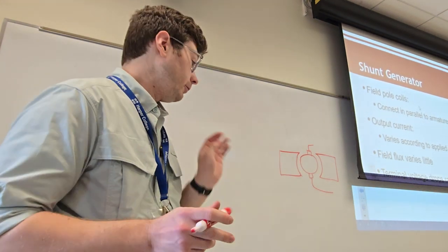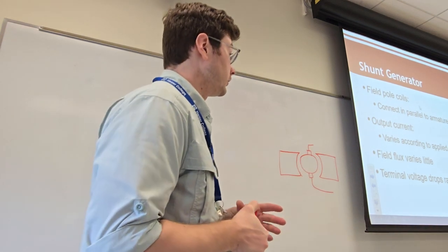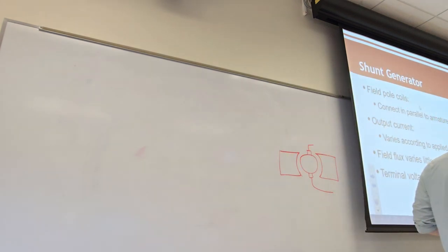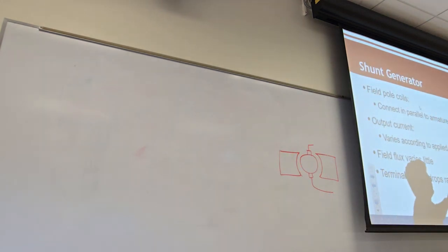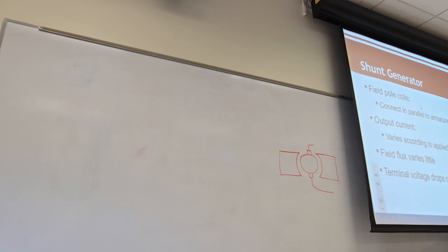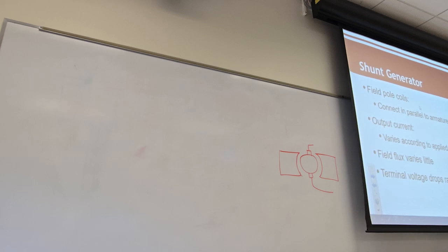All right, so I'm going to whip back for a different generator type, but we're going to focus on this one first because it kind of gets the point across. The things to look at here is that the top part of our armature and one of our field windings are connected. See how they have a common point up here? And both of those attach to one of our inputs. This is the input to our generator, or rather the output of our generator.